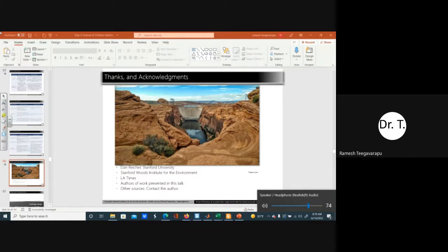Now the accuracy of the forecasts has become much better, because we are using numerical weather prediction models, NWP, radar data, and all other available data to make a very good quantitative precipitation forecast. So if we can predict 10 days in advance what the expected precipitation in that region might be, combined with the soil moisture conditions at that time, then we can simulate different scenarios, go for the scenario which is highly probable, and operate the reservoirs in such a way that they can accommodate the incoming flood. That is what the forecast informed reservoir operation strategy does. It is built to do that job for most of the reservoirs, and they have done pilot studies.